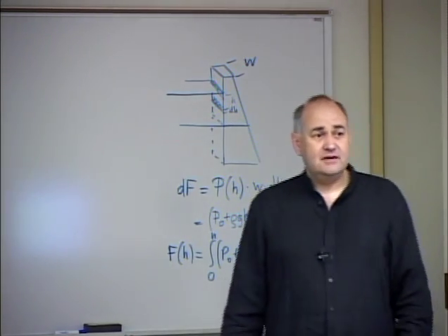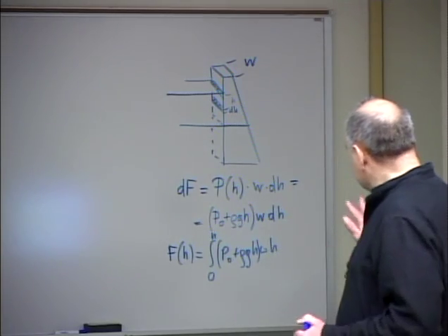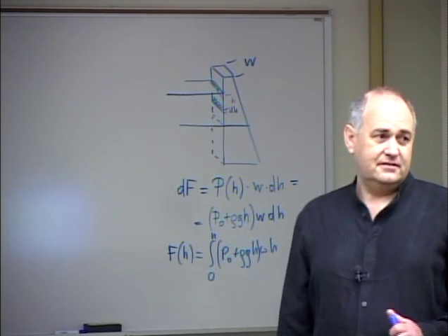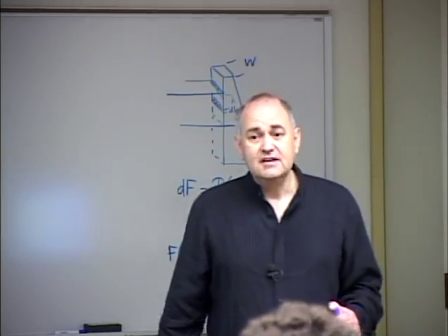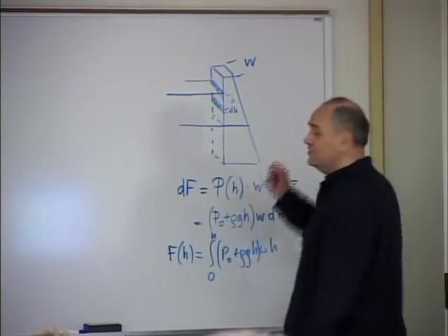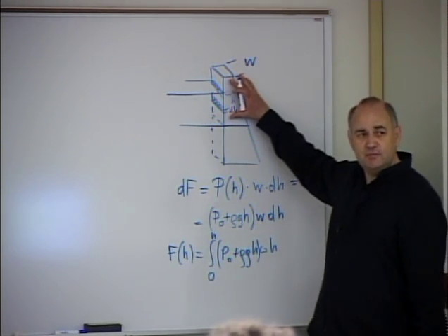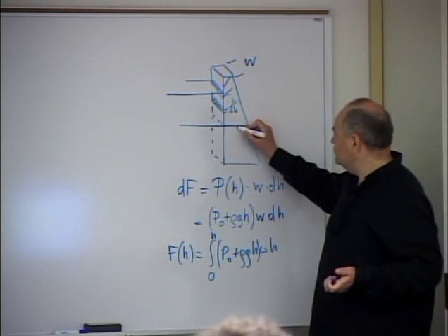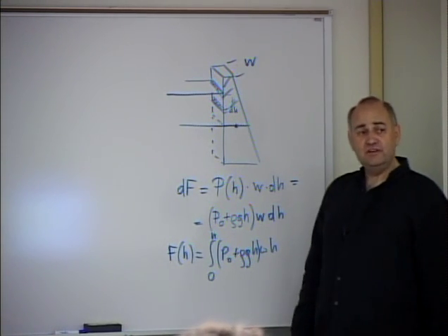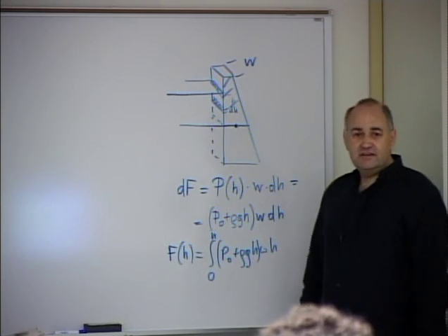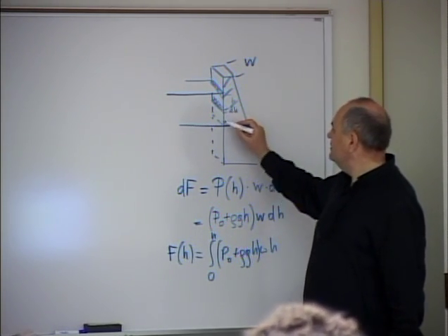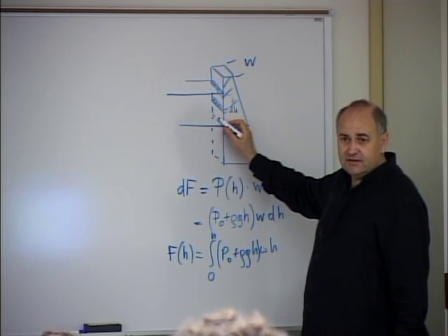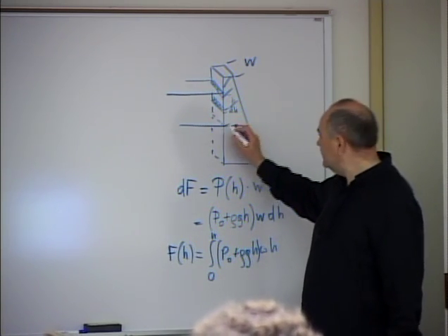We can also think about another thing, because yesterday we were talking only about the shearing stress which is created in the dam. There is also tensile compressive stress, because I could also think about a torque exerted on the top part. If you think about this top part, water exerts a torque. And if I consider just a point, let's say this point over here, the center of it, the center of the force is somewhere between these two levels. It is closer to the bottom because the forces at the bottom are stronger. Right, so we will have a torque.